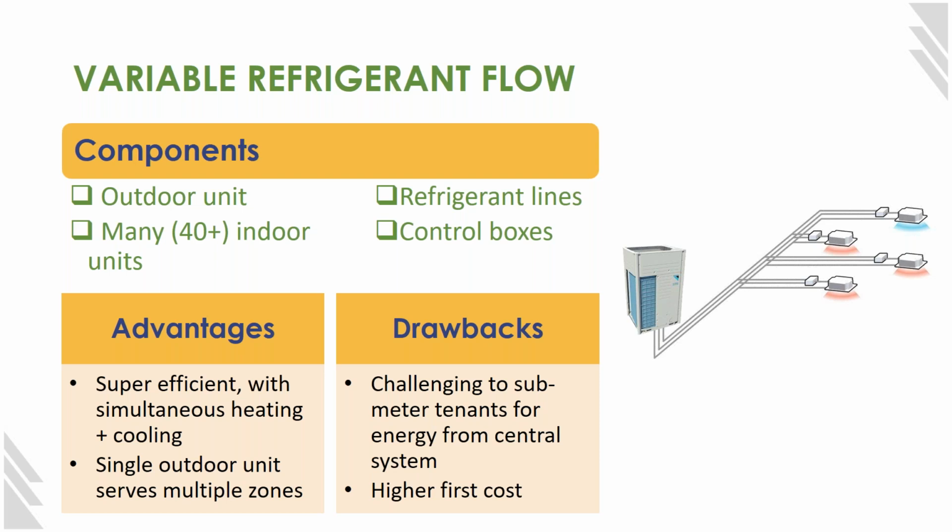You also just have one outdoor unit. Just this one unit here can serve a whole ton of different spaces. So a new construction project of ours in San Jose, recently completed last year, has a VRF system, actually the same system here from Daikin. For a 60 unit apartment building, I went on the roof and they had, I think, 5 outdoor units.